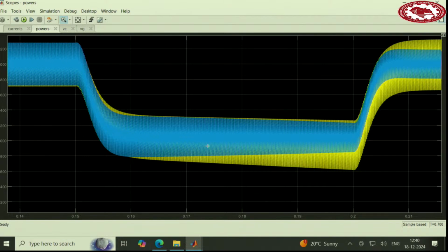in DC systems. It's not common, but because I'm talking about DC systems now, I'm teaching, I thought maybe let's clear it now. But in AC, we know how much inertia synchronous generators provide, so we can really mimic them by the inverter exactly. So we design the capacitor or emulated capacitor in AC to give us the same amount of inertia, or more if we want, that a synchronous generator provides.